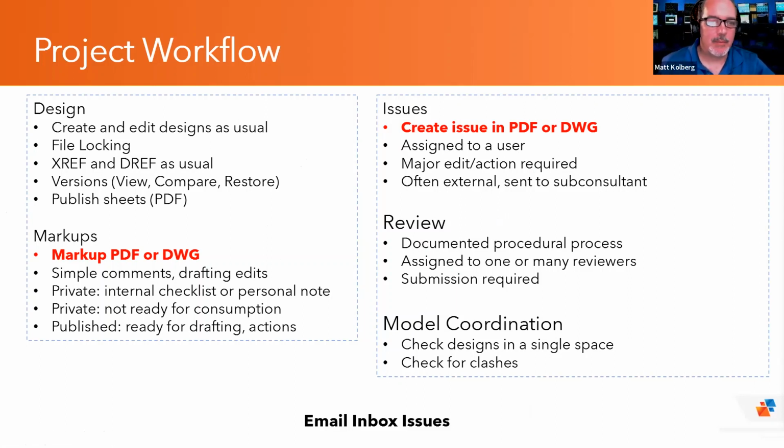The problem is that the DWG isn't the final product. There could be layers on that aren't supposed to be on. The line weights might not be set right. So a lot of my customers prefer still making a PDF first, but the point is you don't necessarily have to.